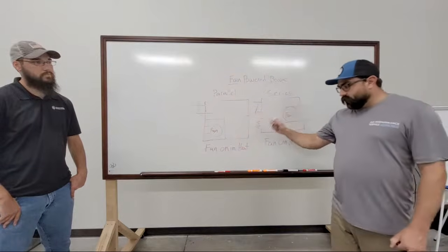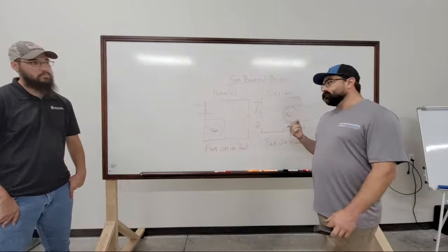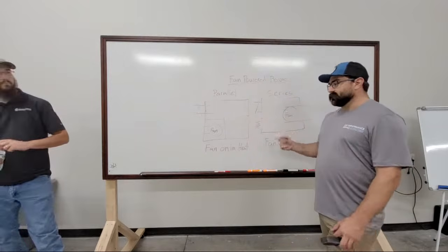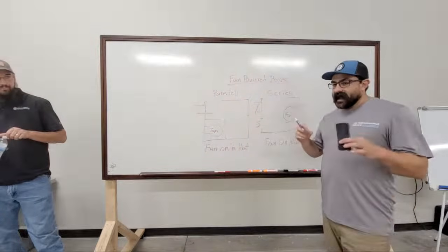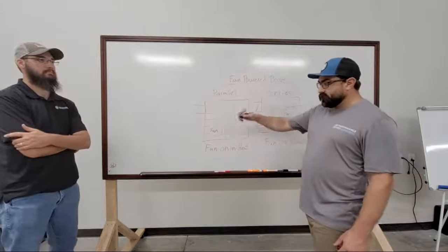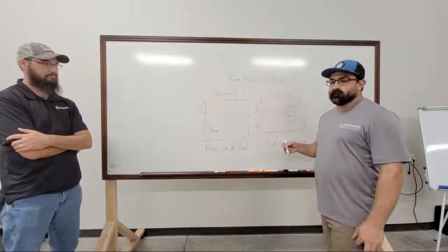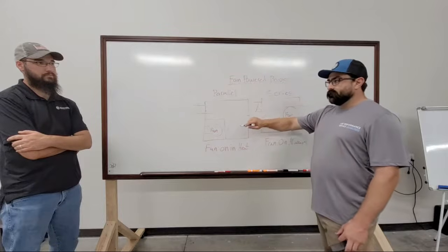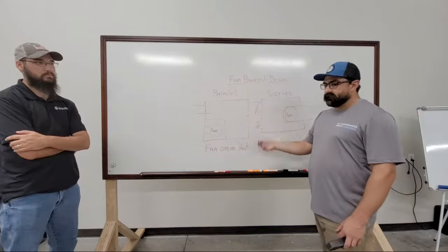Parallel box, your fan only runs in heat mode. Something to note with a lot of control systems, we have dead bands in the controllers where sometimes that fan may bump on and off, even though you're not actually actively heating. The fan is your first stage of heat. It will circulate return air to warm the space up before it brings on a physical heat strip. So just because you see a fan running does not necessarily mean there's a problem. Just because you're over your heating set point, that fan can still be running.